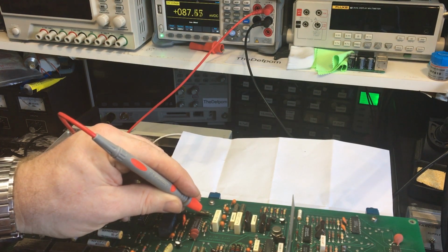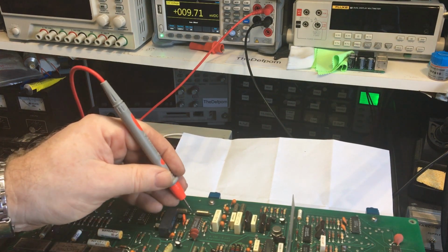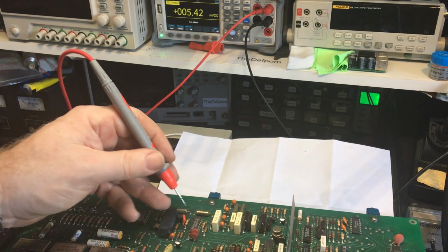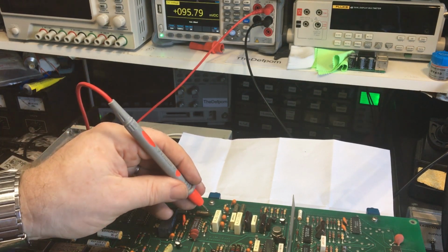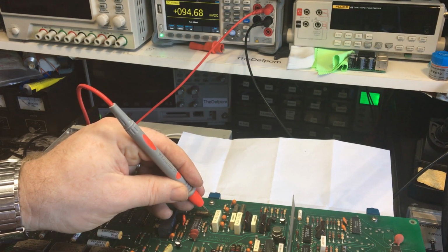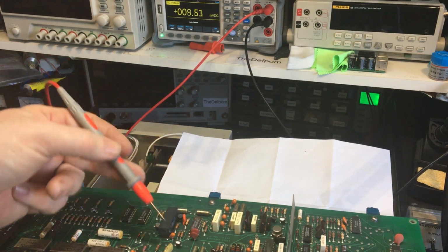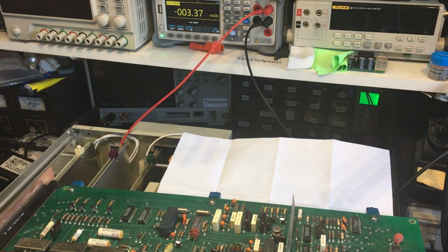Let's see what happens when it's had a chance to discharge, and I'll flick it back over again, see if it comes back up. It does. So it does appear to be switching on that relay contact. Okay. The capacitor is just hiding it a little bit where it's discharging the capacitor. So yeah, I think that's working. So I believe I can eliminate the phase lock input as a cause of the issue.